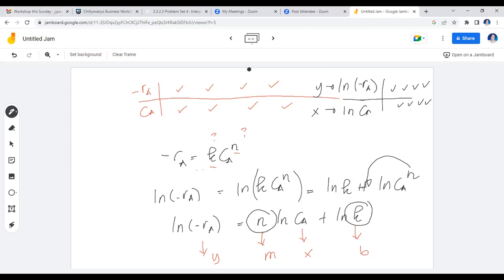So you're going to do differential analysis. It's actually a mix of graphical and analytical approach. It's not purely analytical, and it's not purely graphical. But I think it's 65 to 70% graphical. Okay? It's the way you interpret your empirical set of data for constant volume batch reactor data. If it's variable volume, you also have differential analysis, but with a different set of equations, and it's seldom being used anymore.